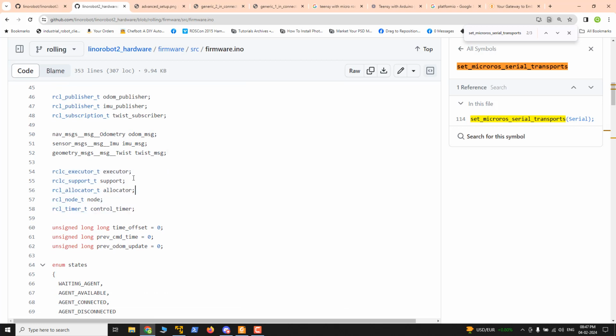Executor in ROS 2, one of the basic examples for an executor is spin. What spin does is it waits for the callback in a single thread. But you can actually run the node in different threads as well, so you can write an executor to configure the execution of your node. If you just want single-thread execution, then spin will be enough. Spin is a kind of execution.